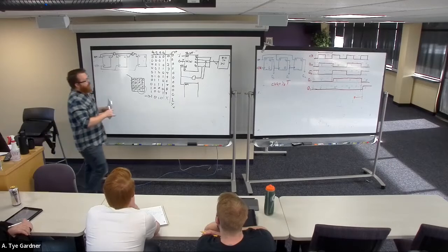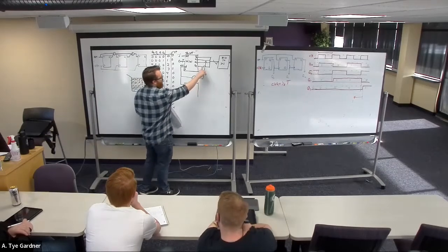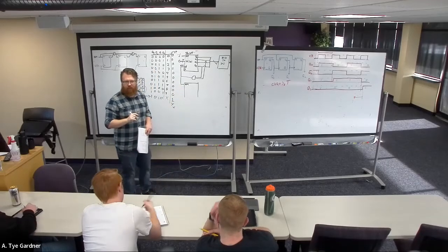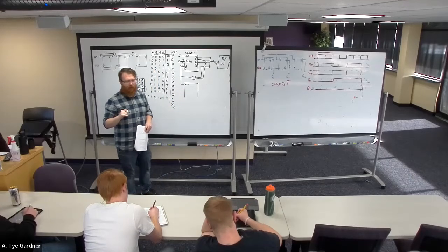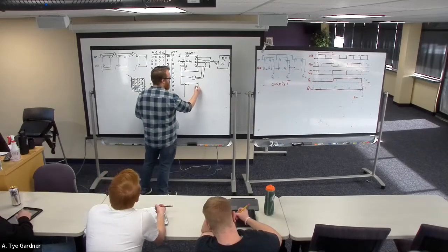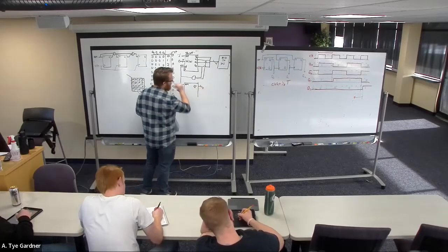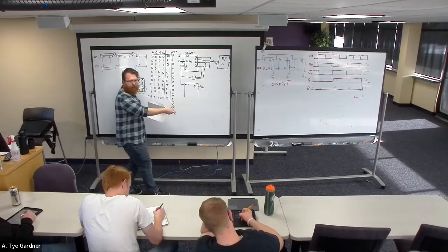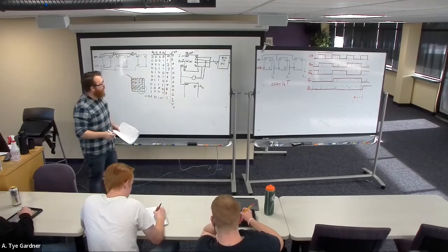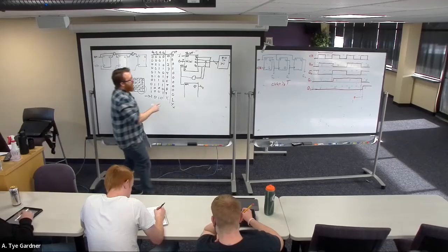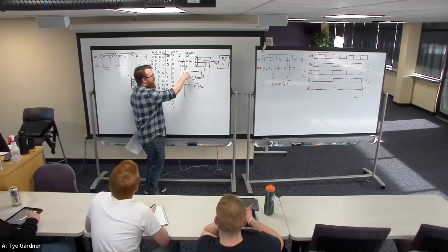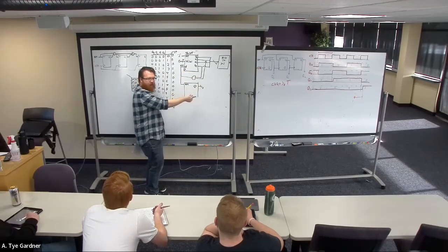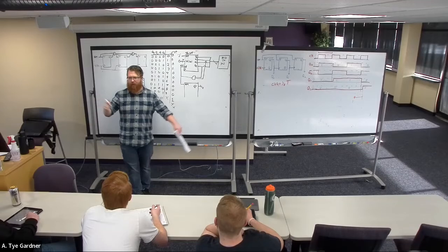Okay, well, now what happens is this one is going to go ahead and trigger the enable and say, you can now go. And then it's going to have the Q, which is a 4-bit number, just the same. And we're going to build the same type of logic that comes back around and feeds it around. But it's the same logic, really. And now what happens is this goes 0, 1, 2, 3, 4, 5, 6, 7, 8, 9, passes the enable, and this goes from 0 to 1. Now we're 1, 0. We just made 10.